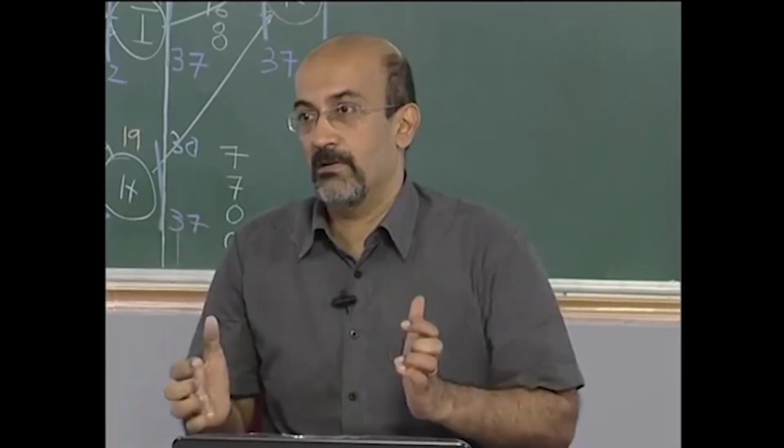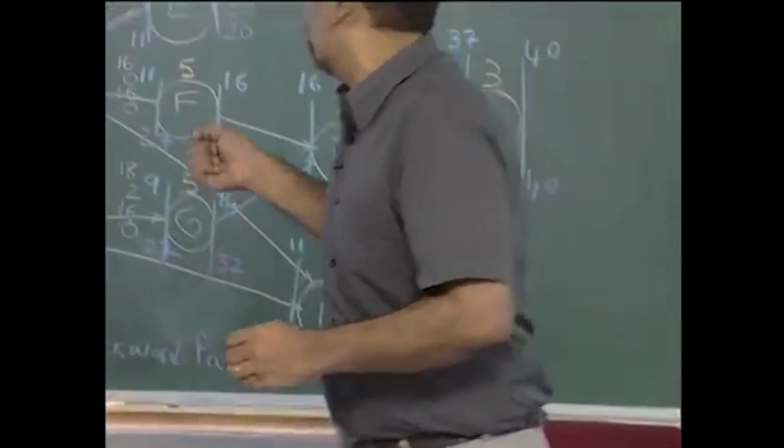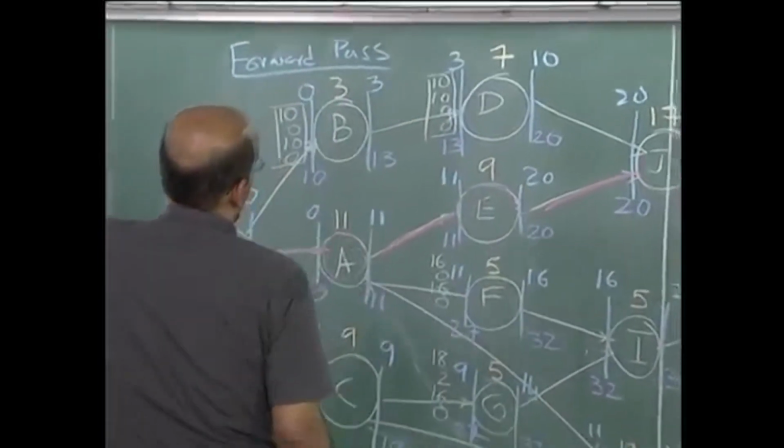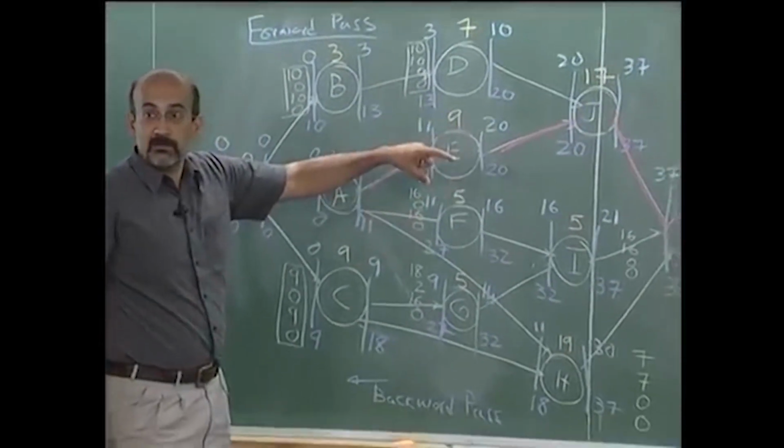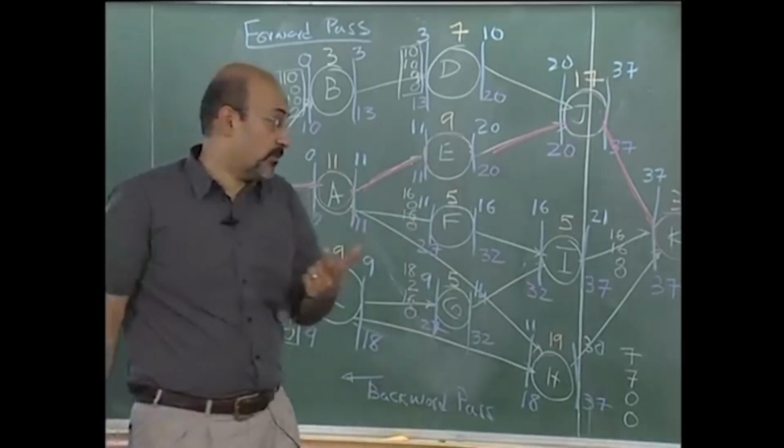So that will delay the project. So we are going to assign it a 0 of independent float, numerical value 0. What you are saying is we cannot afford to have that happen, but even if I take it as a value of 0, it's going to run into problems, right?